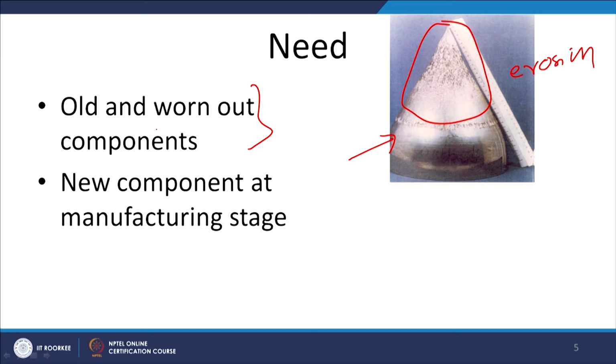So, this is one typical case where surface engineering can be done once the component has been subjected to failure or has been worn out beyond acceptable limits. In this particular case, we will be applying coatings or layers by weld surfacing or thermal spray methods all around the affected area, so that the surface is rebuilt using a material which can offer much better erosion or cavitation resistance.